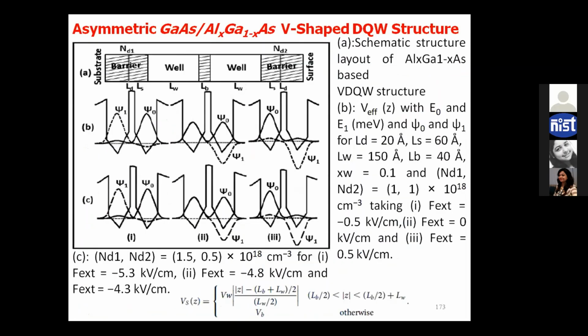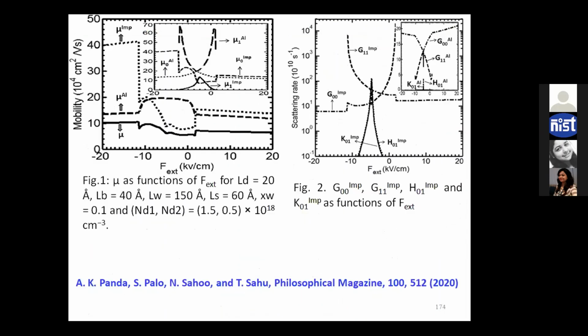You see one of our works in this paper. So here we change this symmetry, and we got the asymmetry in mobility. During double subband occupancy, there is oscillatory nature, and this nature you can achieve at this interaction point. Okay, so this is all about how we can modulate the wave function, that modulates tau, that can modulate the scattering potential, which also modulates the tau, and that can modulate the mobility, which can modulate your current density in the device.